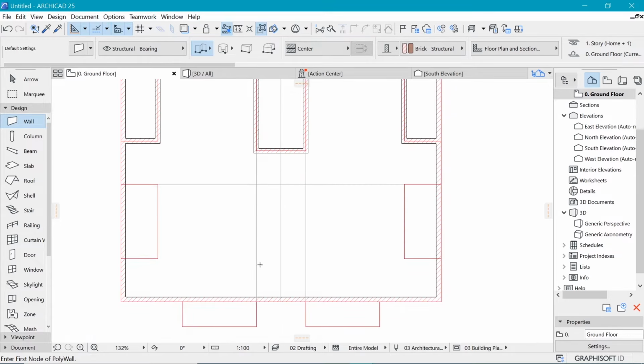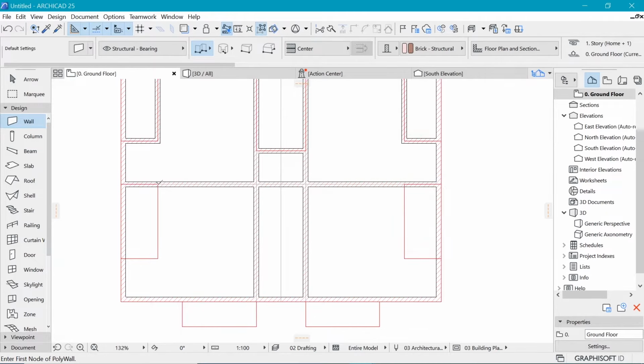And then we also want to continue this wall all the way to this other side, so we make that, we double click to finish and create this one as well, and we go ahead and put in the walls essentially in the elements that we created, and this one as well here, and on the left side as well like so, and double click to finish.